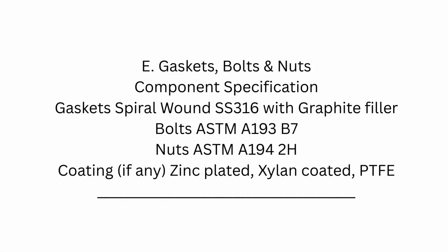Gaskets, bolts and nuts, component specification. Gaskets: spiral wound SS316 with graphite filler. Bolts: ASTM A193 B7. Nuts: ASTM A194 2H. Coating: zinc plated, xylan coated, PTFE.